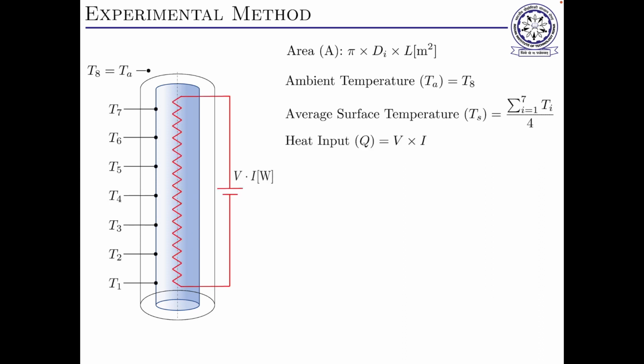Now what we'll do, we will start to heat this solid cylinder, and this is an enclosure, so that outside air does not affect our system. So the air will get heated up, and slowly it will start moving upward, so some bulk motion will start. After some time, after steady state conditions are achieved, we will get these things.